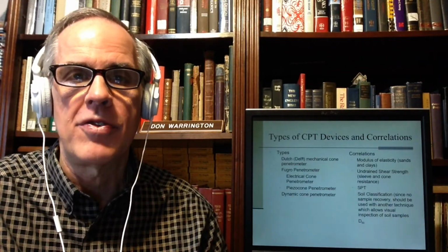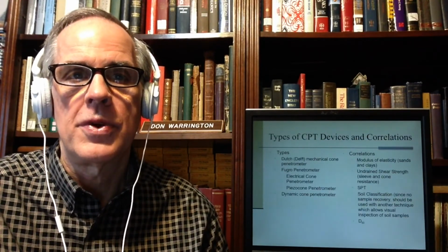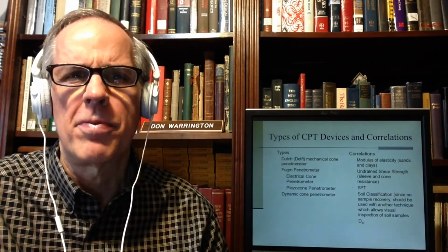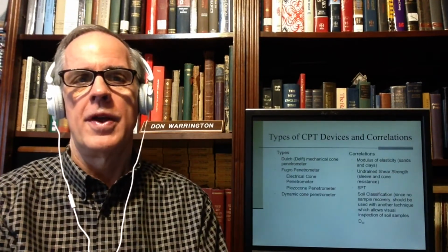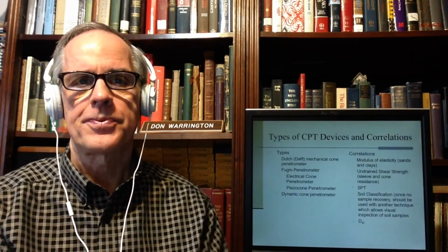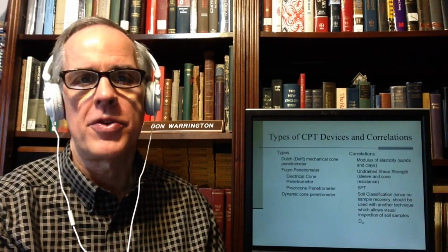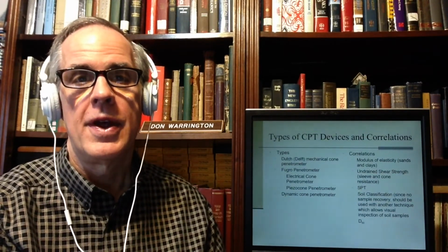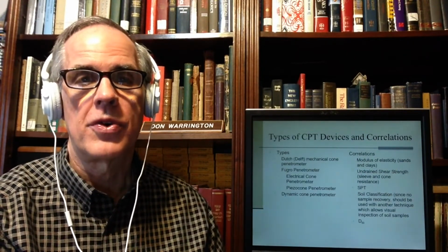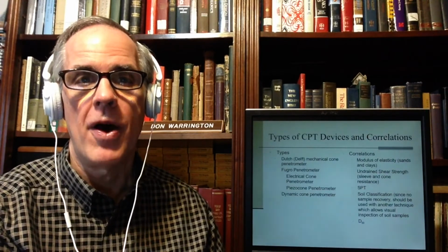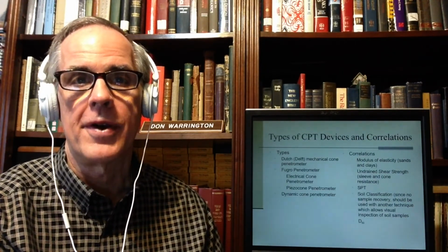It's used mostly with pavements and that sort of thing, but it's also very useful for showing students how cone tests and impact tests work, without having to spend on either a cone truck or an SPT drill rig.